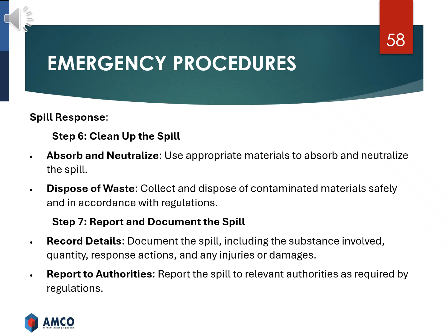Step 6. Clean up the spill. Absorb and neutralize. Use appropriate materials to absorb and neutralize the spill. Dispose of waste. Collect and dispose of contaminated materials safely and in accordance with regulations. Step 7. Report and document the spill. Record details. Document the spill, including the substance involved, quantity, response actions, and any injuries or damages. Report to authorities. Report the spill to relevant authorities as required by regulations.